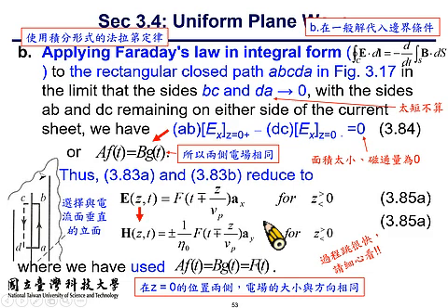All right. So using Faraday's law, we understand that AF and BG are the same, at least at z equal to 0. And so we can have the formulation for the magnetic field intensity H. It becomes positive and negative 1 over eta times the F function.